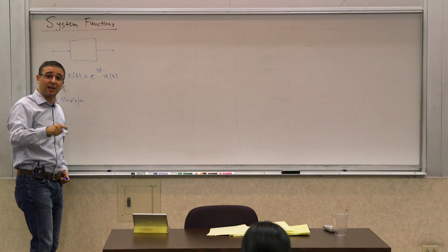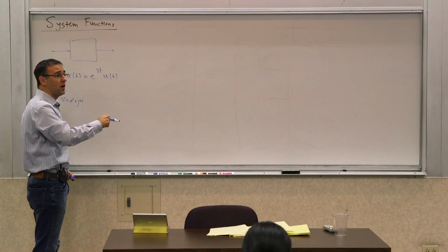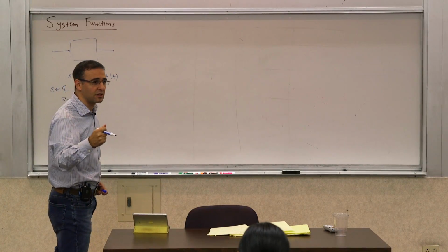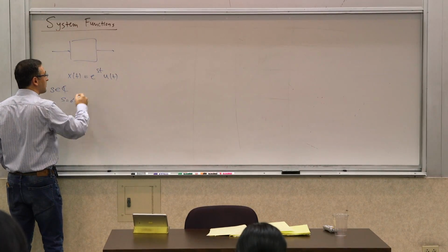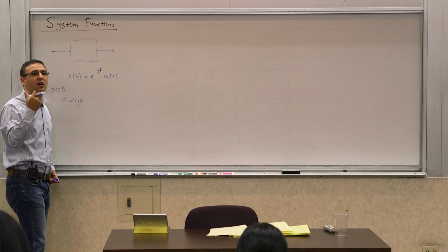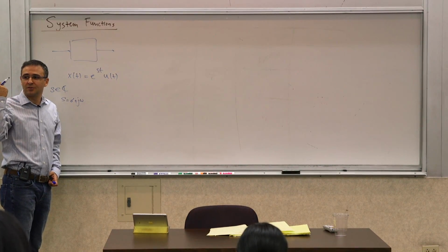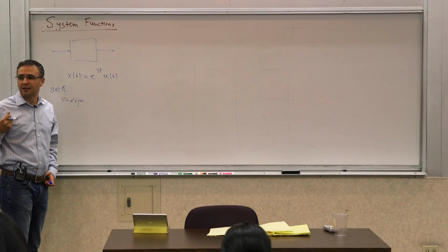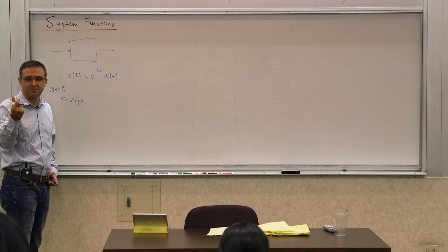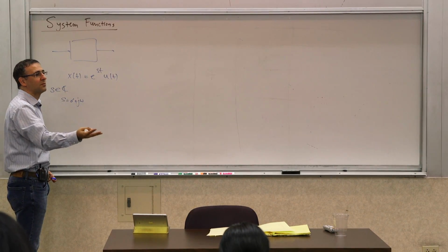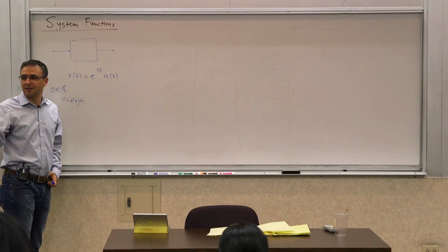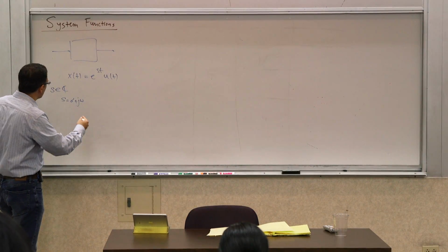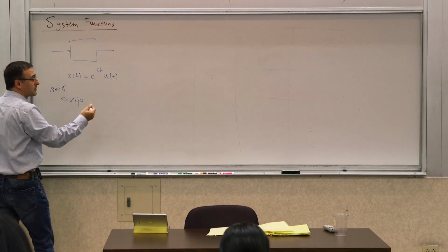It also subsumes the exponentials, the regular exponential, or more combinations of those, basically exponentially decaying or exponentially growing sines and cosines. So this is a useful thing to look at, because we saw that because of the fundamental theorem of algebra, the system responses would really fall into combinations of these. Because when you factor them, when you do partial fraction expansion, you will either have first or second order polynomials with real coefficients in the denominators of your elements, and they can only produce these kinds of responses. So this is a useful and pretty powerful thing to do.